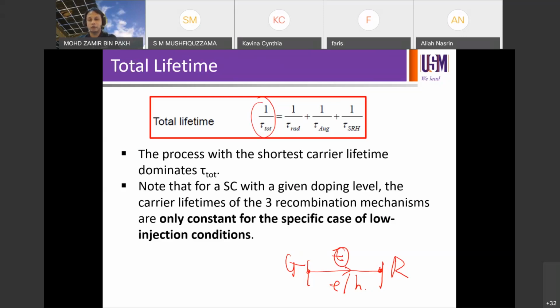Gallium arsenide, heavily doped, without defects. You heard the description. Gallium arsenide, heavily doped, without defects. So what sort of recombinations do you have? Okay, Auger, anything else? Gallium arsenide. Look at my material: heavily doped, no defects. So what are the dominant recombination mechanisms from these 3 characteristics of the semiconductor material?